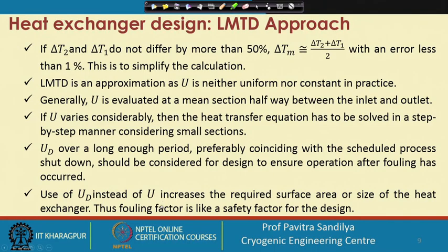Even though we are using UD, it essentially gives a higher heat transfer area. So this fouling factor may be taken to be a kind of safety factor for the heat exchanger design.